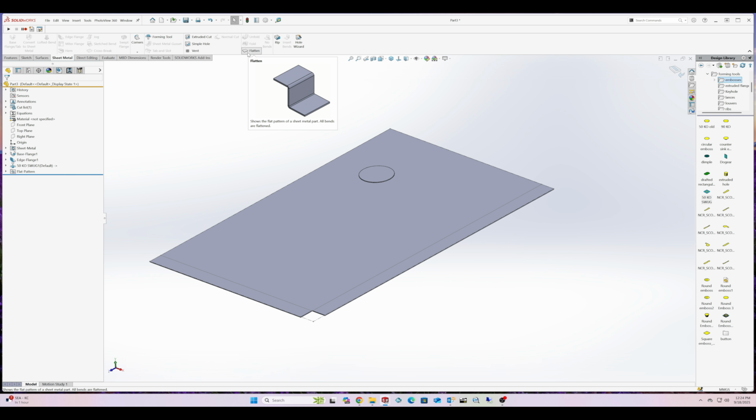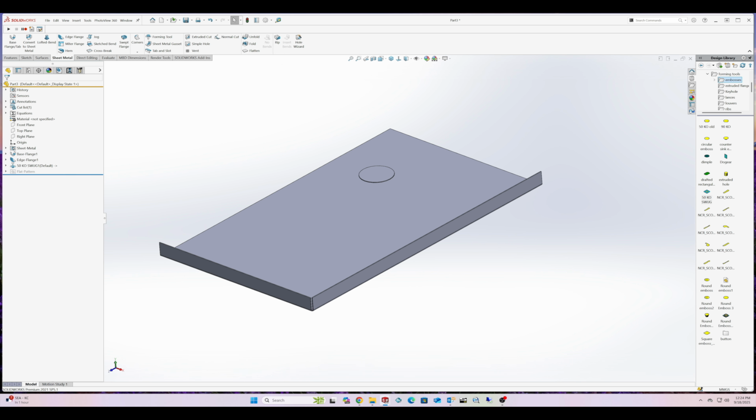And I'm going to touch on a thing right here that some of my group asked when we were doing this. We're using a form tool right there. If you're using CNC punching, more and more we're getting into lasers. When you get into lasers, you're not necessarily going to have form tooling unless you've got a laser punch combo. And with that knockout there, you're going to have to create a punch pattern or a cut pattern, excuse me. You're going to create a cut pattern to where you go in there and you cut this knockout out.